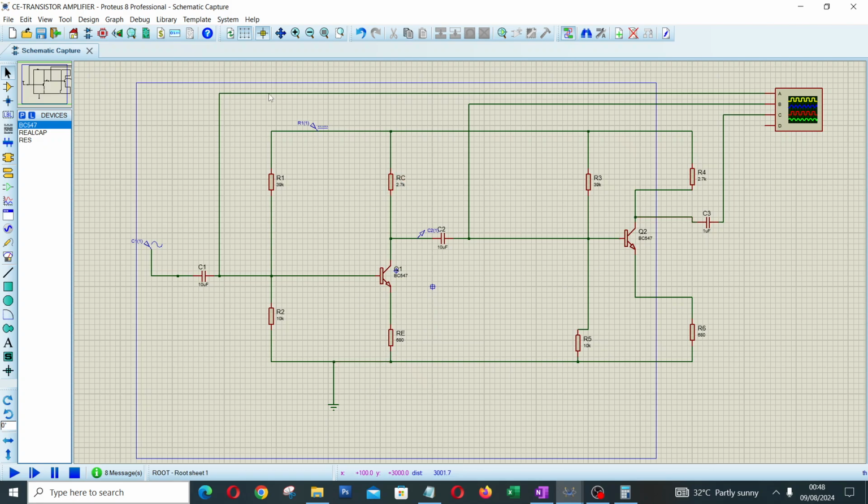So now what I did is I just duplicated this circuit. It's the same thing here. The same values that I put here are what I put here, because I want the amplifiers to have equal gain. So the only thing I've added is another circuit. Let me separate this circuit now so that we can measure the amplifier gain.